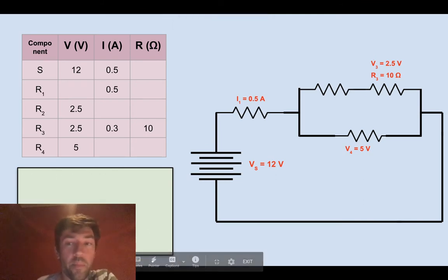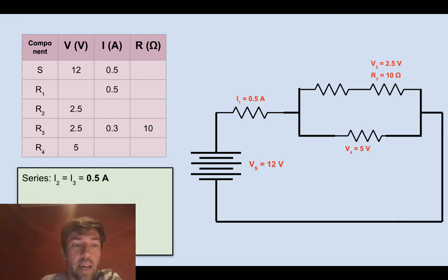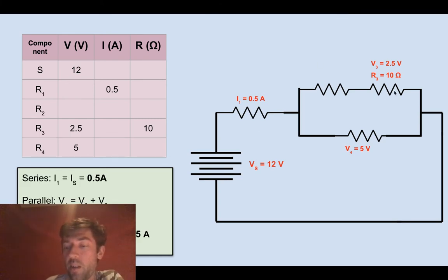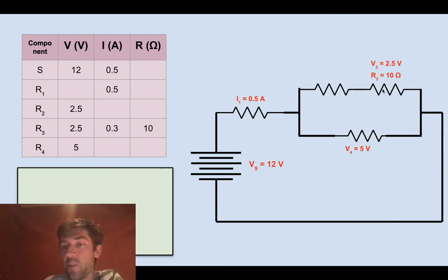There are the filled in numbers. Okay. So that last part that I just solved, 0.25 amps right here. Well, this resistor is in series with this resistor, so they have to have the same current. So that current there is 0.25 amps.